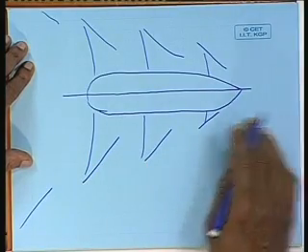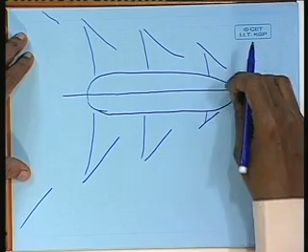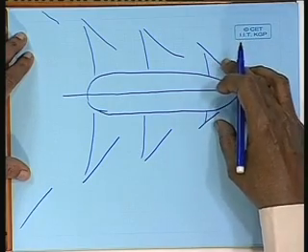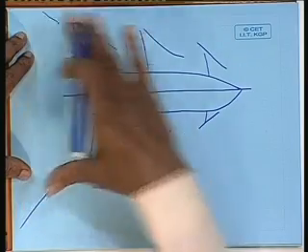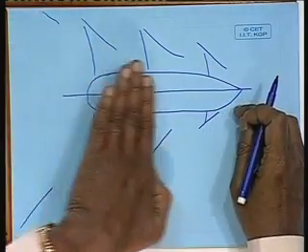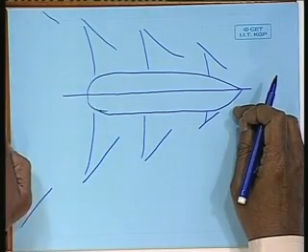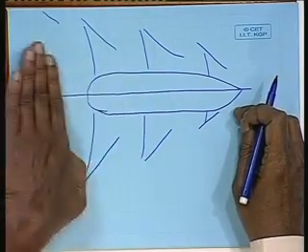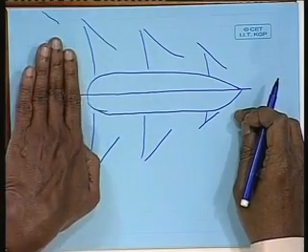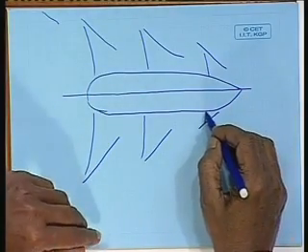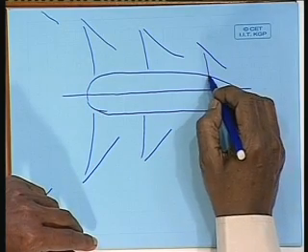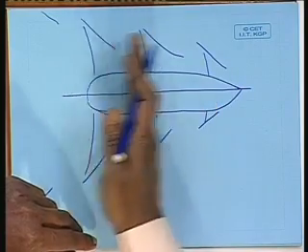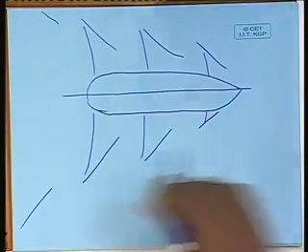Okay. Now, as we have explained, if it was created due to the forepart, if the forepart could be represented by a pressure point, then these waves would be created. Okay? And we have said that the transverse waves reduce in height as it goes forward. So, as the waves are further aft from the ship, the height reduces. So, if you look at the vicinity of the ship, you will find a large wave crest somewhere here, as the diagram shows, and the wave crests will be there as you go aft looking at the ship's side, but they will reduce in height.